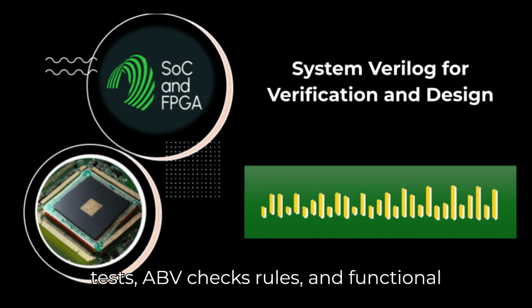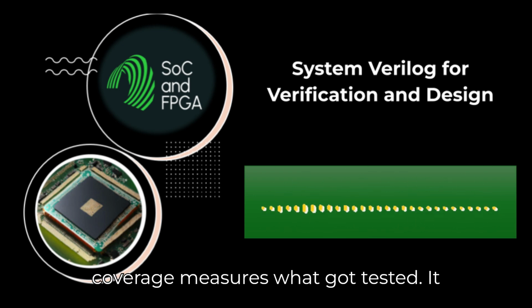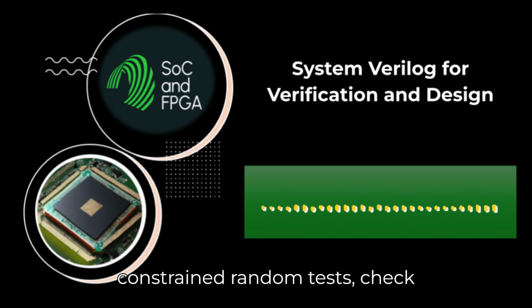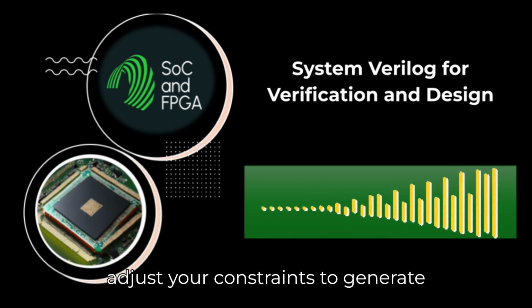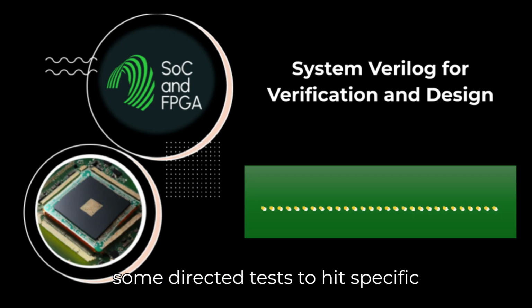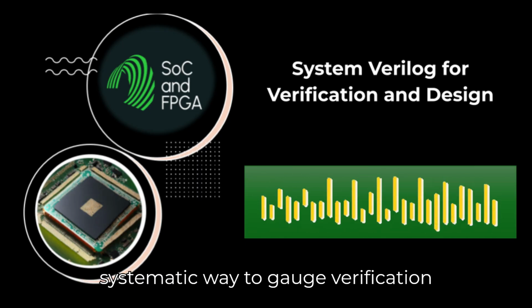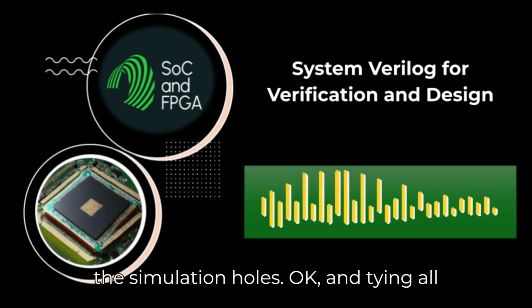So CRV generates tests, ABV checks rules, and functional coverage measures what got tested. It sounds like a closed loop. It is. You run constrained random tests, check assertions, and measure coverage. If the coverage goals aren't met, you might adjust your constraints to generate different random stimuli, or maybe write some directed tests to hit specific uncovered scenarios. It provides a systematic way to gauge verification progress and completeness, and helps you find the simulation holes.